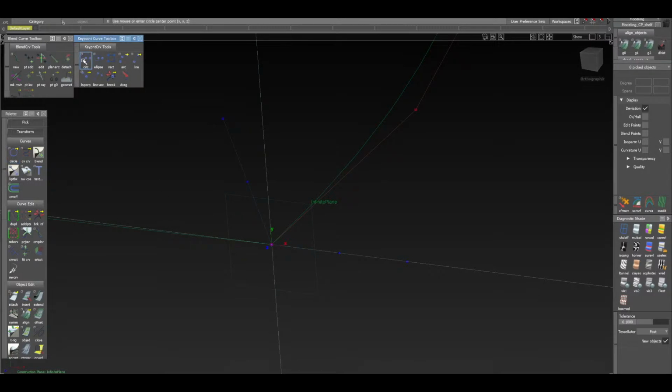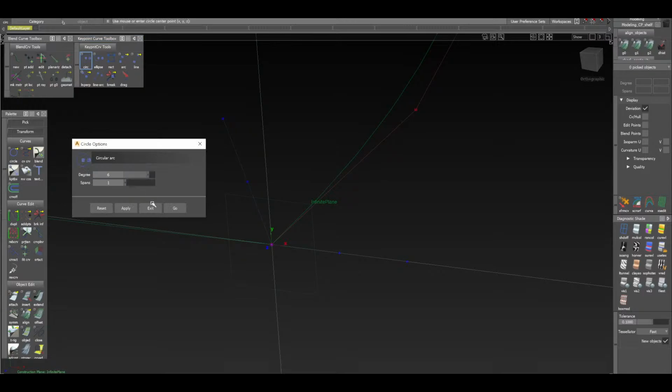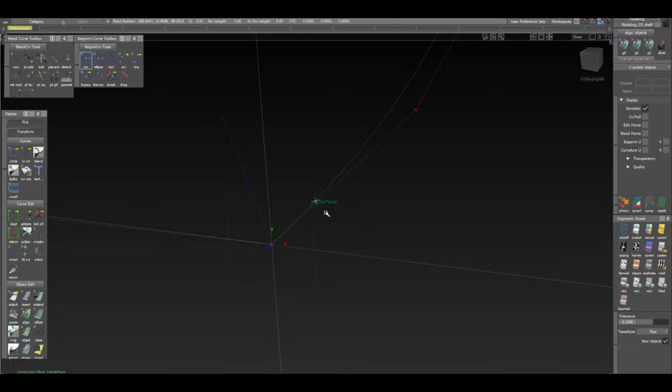Okay, so I'm going to click circle. And to be totally honest, I don't know how the software is going to react to this. But we're going to try it anyway. Okay, great. So I'm holding Control and Alt, and Alias has recognized either the edge of our surface or the fit curve. Either way, it shouldn't really be a concern for us. So I'm going to drag this axis point all the way to the base of either the fit curve or the rail surface, and I'm going to let go.